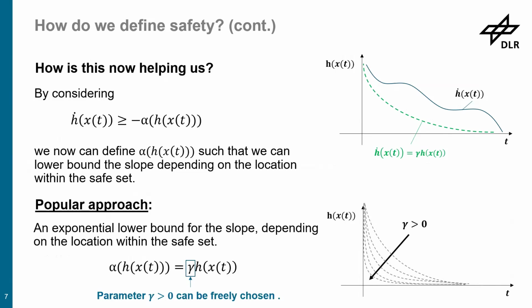This is for a first order system, but if you choose a gamma that is very high, you search for an exponential function that goes very close to this direction. And the further you go in this direction, it means your safety constraint becomes active later, very close to the boundary. This has some implication on your actuators, since you have control input limits, but it also makes your safety filter less conservative.